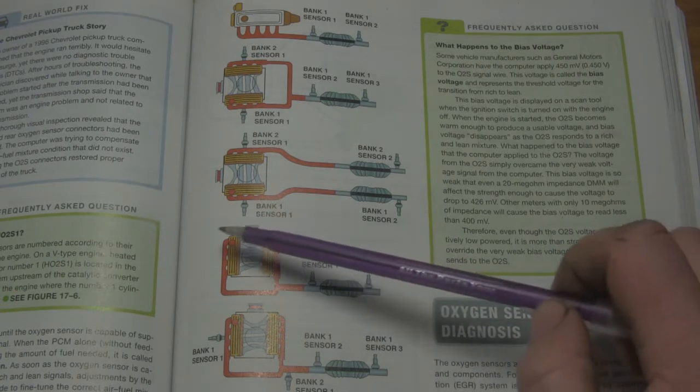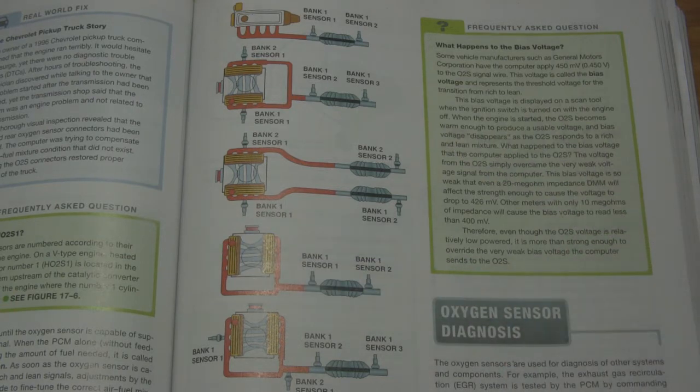So you'd have the driver's side and the passenger side air-fuel ratios being affected, that oxygen sensor data being affected by that misfire. With the addition of a second bank, splitting that engine into 2 sections, we can actually tune one side and try to trim it out a little bit better for that misfire and leave the other side completely alone.